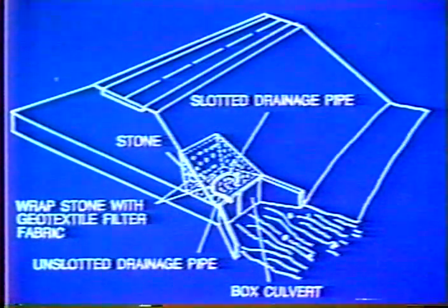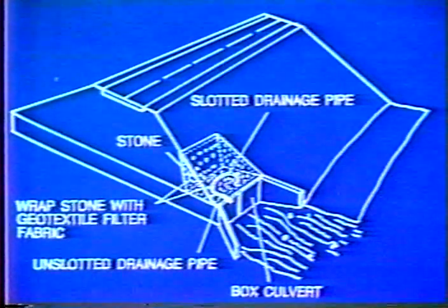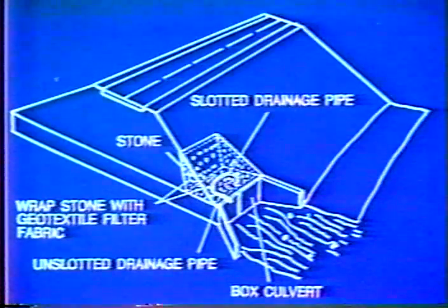Obviously, here again, you need to work real fast if you're excavating the toe of the slope out. Don't waste any time. Don't go smoke cigarettes or that sort of thing, but pay attention to getting that backfill in as fast as you can. Now, in certain situations like this, you may have to have some kind of a clamshell or something to remove the material. But it illustrates an important principle.